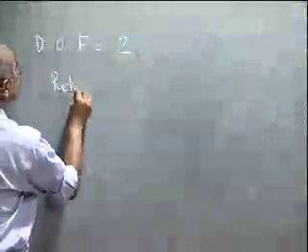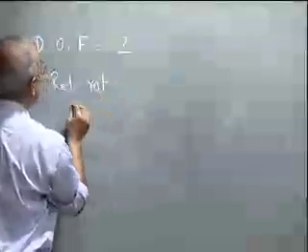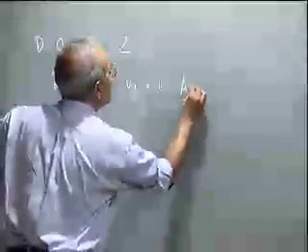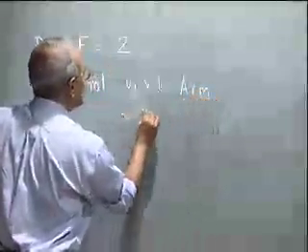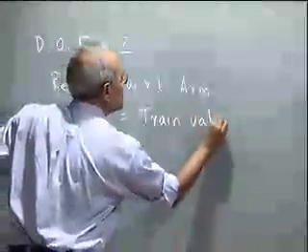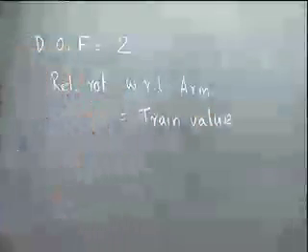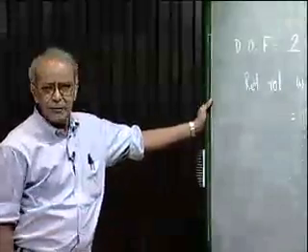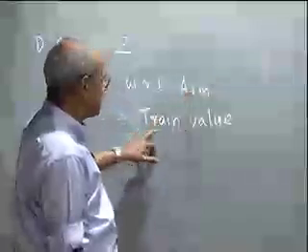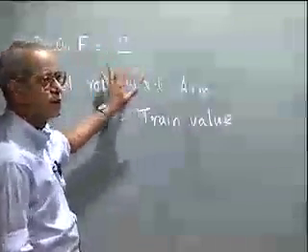in our next lecture. To analyze this epicyclic gear chain, the only thing to note is that the relative rotation of the gear with respect to arm is equal to what we call the chain value. That is, as we get normally in a simple gear chain or compound gear chain using the number of teeth. So it is the relative rotation with respect to arm that is given by the chain value, not the absolute rotation ratio of two gears.